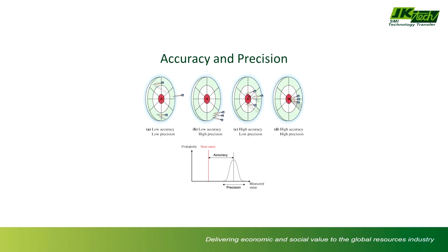A slightly more mathematical representation is you have your body of measurements. It's however many you take, 6, 3, a dozen. So you have a population and that's your measurements. Your accuracy is how close you are to the true value, and your precision is the spread of those results. Obviously, we would hope our results are much closer to the true value than that example.